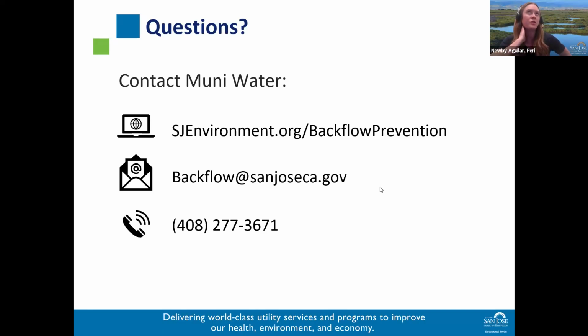A common situation, like I said, that came up a lot in this presentation, is a submerged hose. It's probably the most innocent of acts and ends up being something that can be detrimental, right? So it's a really quick fix too. Just take your hose out of the bucket or create what we call an air gap, where it's hanging over the bucket and it's not submerged.